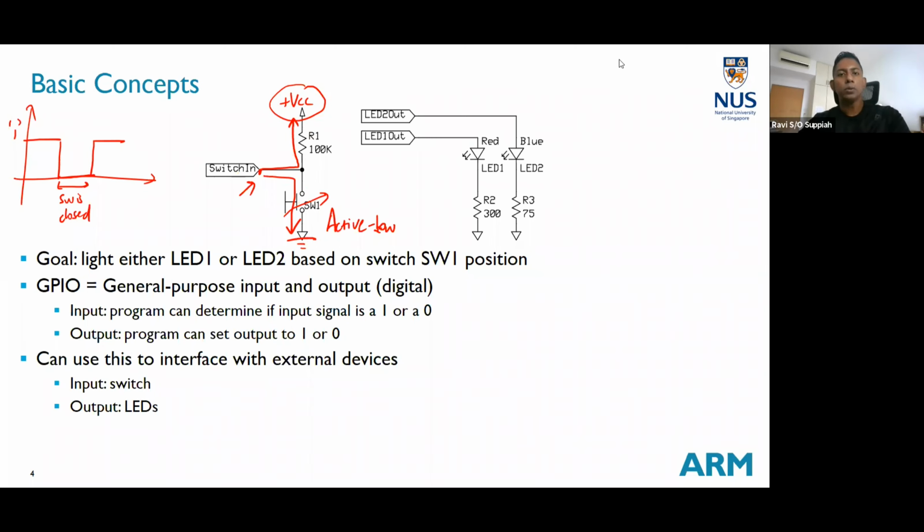For question 2, the logic level to turn on the LED, 75% say 1, 25% say 0. Again, you just need to see that the pin here is connected to the anode of the LED, and you want current to flow from anode to cathode for the LED to light up.